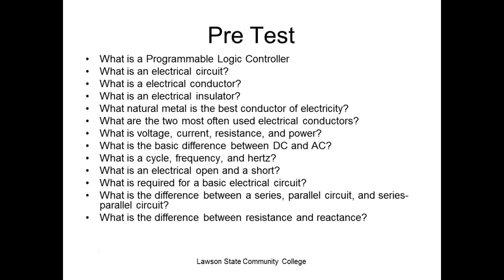And series parallel. Combination of two. Series parallel will run into electronics a lot. We have these devices we call solid state devices. Transistors, SCRs, triacs. These guys have to be biased to turn them on, to make them operate. So you have to put precise dosages on. And we do that with resistors, series parallel circuits. So if you're in the AUT degree, you won't take that. If you're in the ILT degree, you will take it. You'll learn how we use these resistors, these series parallel circuits to bias these solid state devices.